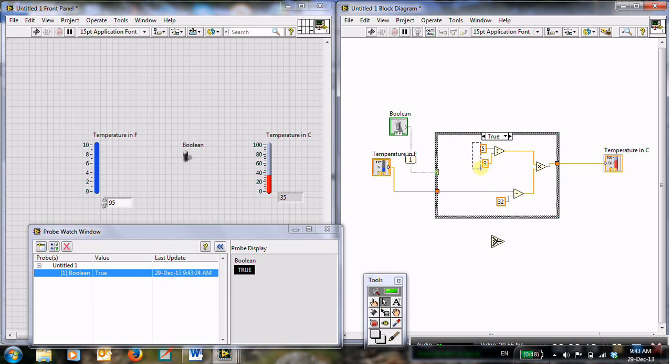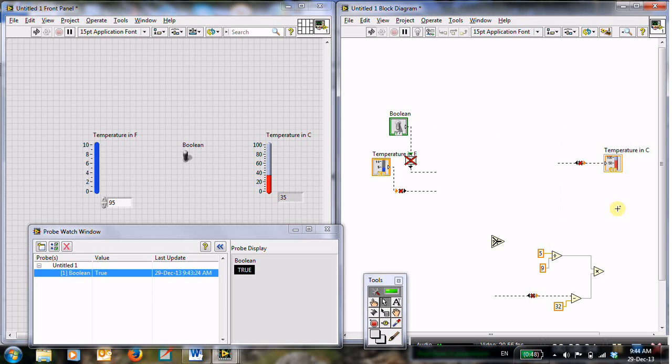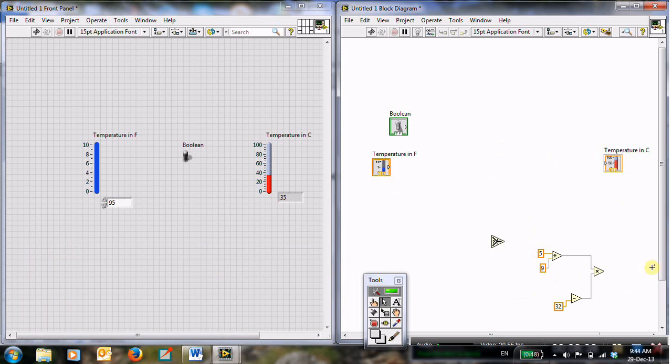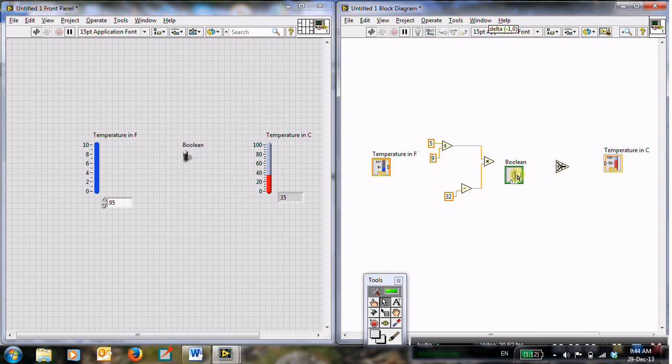So be careful, you have to connect these things. Look here, this is Control X, and you can put them outside, anywhere outside. This is Control V, and here let me just delete the case structure. I deleted, and then Control B to remove the wires here, and now let me just move it again. So what do we have now here? This is the select. Here, look, this is true, and down this is false, and in the middle this is the Boolean input. The Boolean input, it will be from here. You can put it here, it's better, yes, and then connect it to the Boolean input.